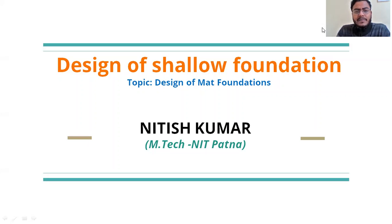This assumption is valid when the raft or mat is resting on the soft clay. If the mat or raft foundation is not resting on the soft clay, this assumption will not be valid. For those cases, we can go for the elastic method. In this lecture, I'm going to discuss the rigid beam method, which means we have taken the assumption that raft is infinitely rigid and the pressure distribution will be linear.